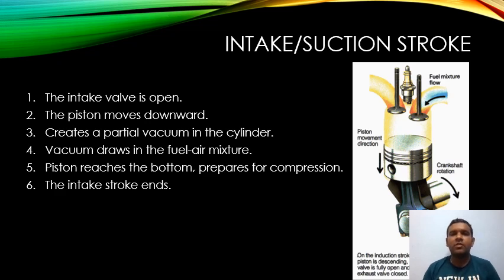Now, let us look at all these four strokes one after the other. The first one is the intake or the suction stroke. Here, the intake valve is open in the engine. This part is the intake valve, and it is open during the suction stroke. The piston moves downward.